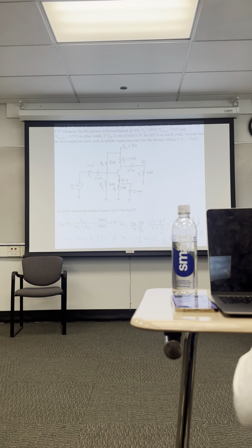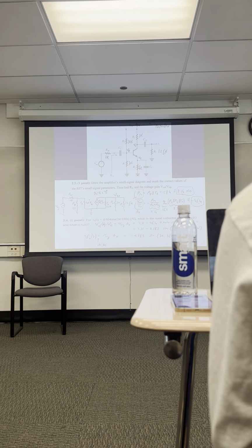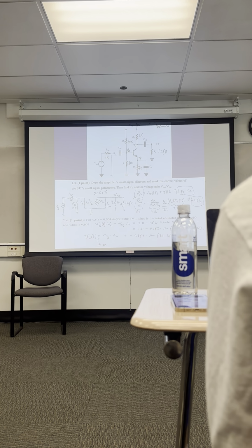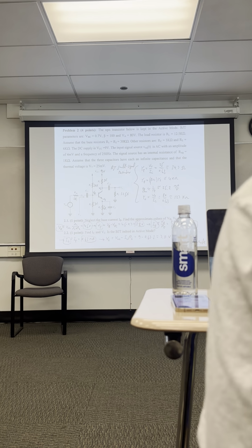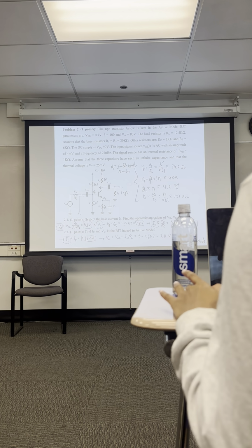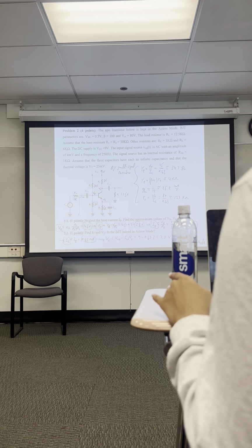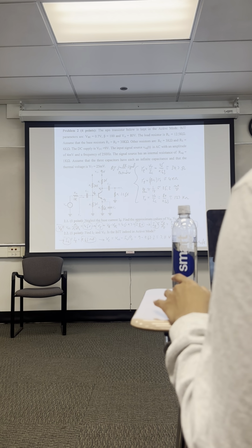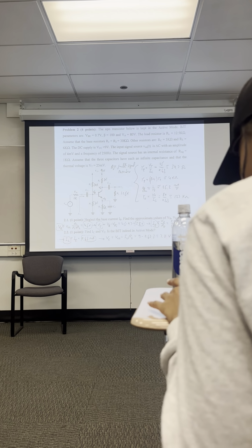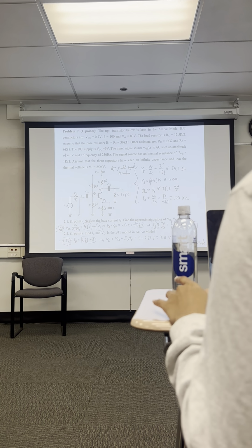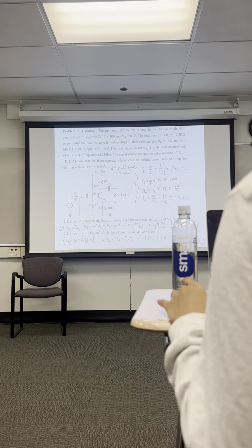Now the MOSFET amplifiers are definitely more challenging than the NPN transistors. And part of that is that in MOSFET there's no miracle equation. So there's no I sub C equal beta I sub B. MOSFETs have their own set of equations based on how the transistors are actually manufactured.